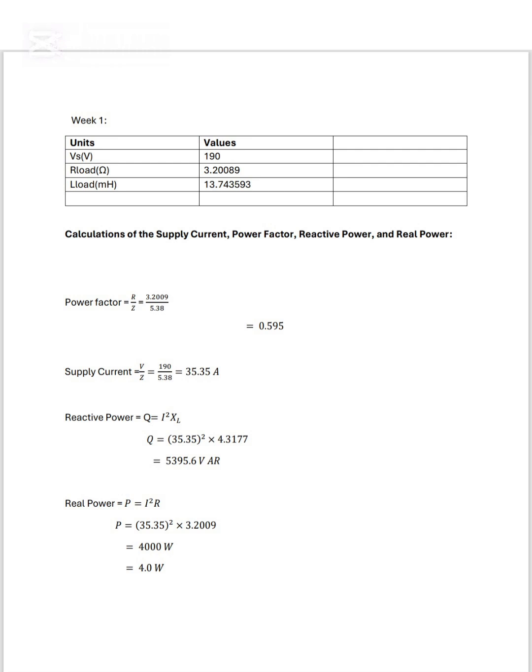A low power factor, an example of which is 0.70, means 30% of the energy being drawn is effectively being wasted as heat or unnecessary current. And a solution for this is power factor correction. Local neutralization is when capacitor banks provide the necessary magnetic energy locally at the machine, rather than drawing it from a distant power plant.